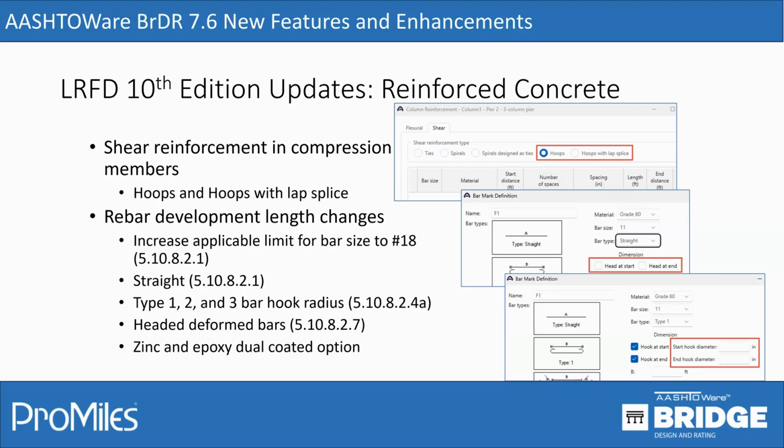Also, in the rebar materials window, there is an option to, I think previously we had epoxy coated option. Now we have zinc and epoxy dual coated option as well to be considered for development length calculation.